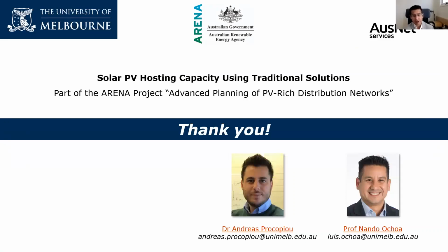We have a very interesting set of results for the other networks, particularly the SWER lines, those that are rural, and it is quite interesting to see what is actually happening to the customers, to the voltages, etc. Also, please note that this webinar did not present what is happening when we use the on-load tap changers at the primary substations, at the zone substations, but this information is all in the corresponding reports.